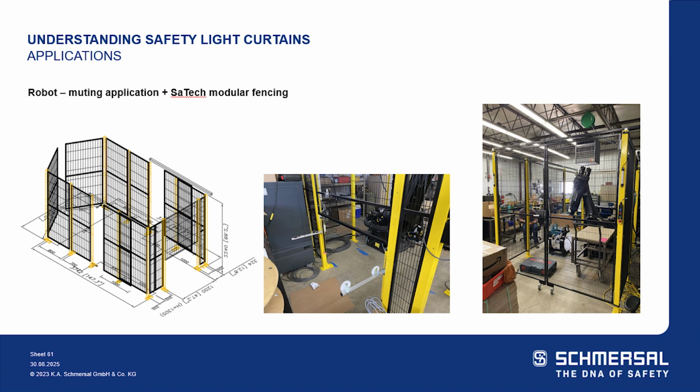So they utilized that full Schmersal solution, including our 445 series with the muting sensors. It allowed the customer to pass the conveyor through the opening with uniform thermoformed parts through an enclosure where the robot was able to pick and place the parts throughout the process. The conveyor in-feed greatly increased their throughput, removing the necessity to shut down the robot to load the parts. Though there was a gap in the guarding, the easy muting offerings that we have in the SLC 445 allowed them to maintain that higher safety rating while minimizing any bottlenecks in their production.